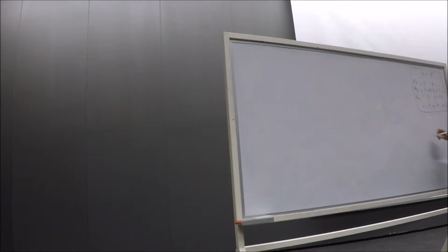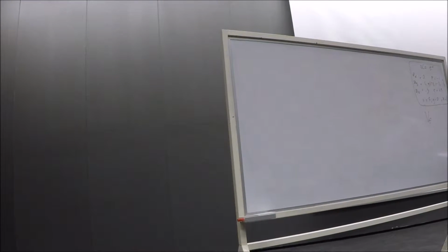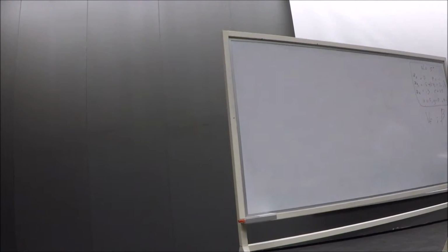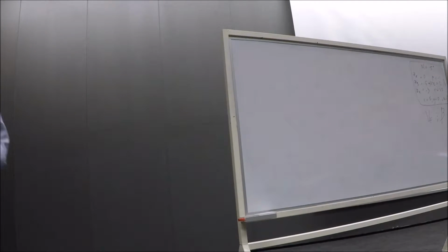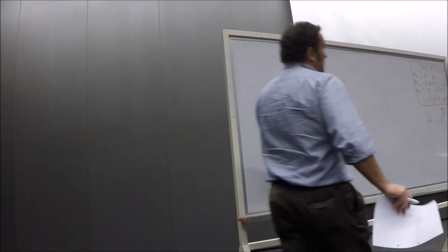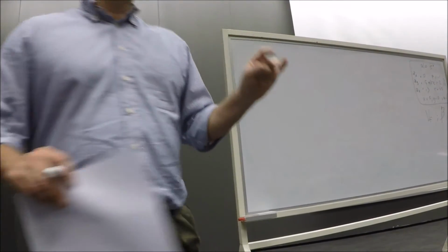What we have to do is to reconstruct, so determine the airspeed, V, and the side slip angle, beta. So we need to find these two parameters using the kinematic equation given in the question. So what we need to do here is to simply take the values that are given in the question and substitute them into the kinematic equations that you have been given.